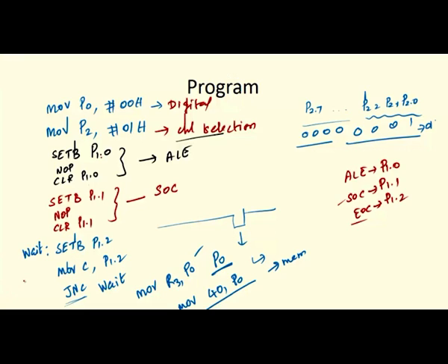Suppose I ask you to read the data from the 4th channel, what will you do? For the 4th channel, I have to give the bit position 100, which you read as 4. So, instead of 1 I have to give it as 4. Okay. So, this is one way: by changing the channel we can read it.